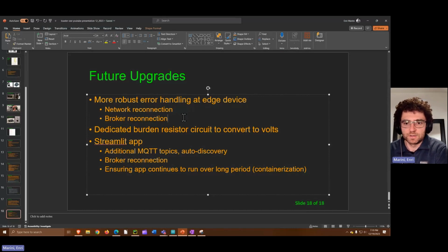Similarly, do we instantiate a new connection to the broker? Are you storing network credentials locally? In the case of the Arduino, you can use a library that encrypts the network credentials to the EEPROM memory, which has a limited number of read-write cycles, but even if somebody had physical access to it, that data would be encrypted.